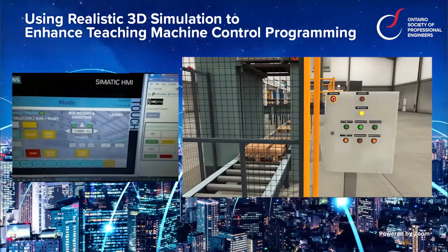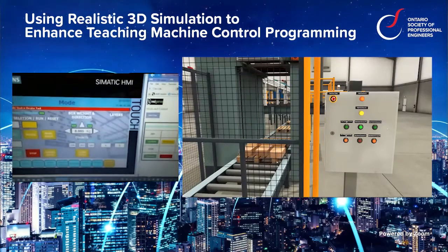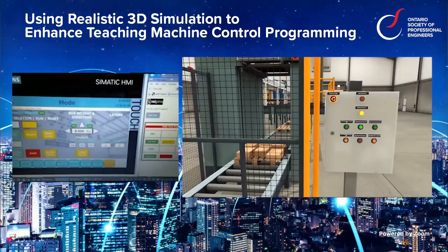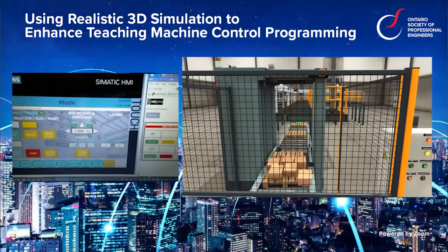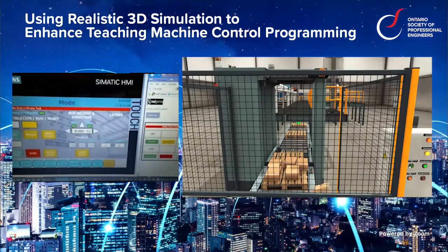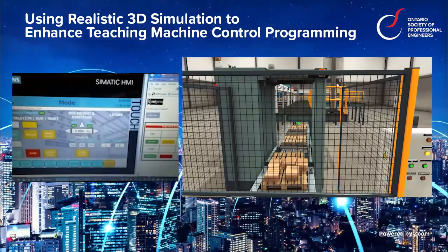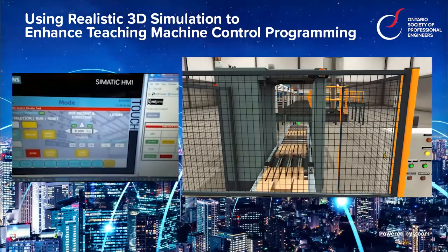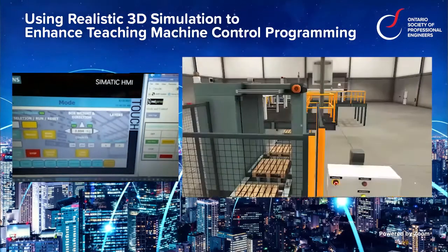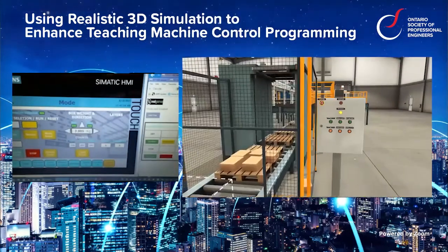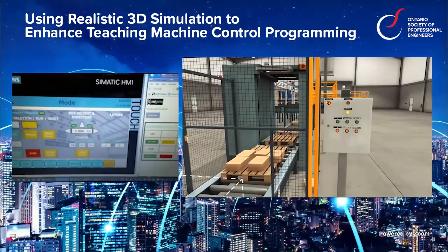And you see it's pushing, and because I've messed up on how I turned the motors on, the vibrations are pushing the boxes off the pallet. So again, they're reacting very much like you'd have in a real world, where you've got pallets running into each other. I've pressed the wrong buttons. I've done the wrong thing here in manual mode, and kind of demonstrate how important it is to create a system that an operator can't mess up. So I probably should have had some sort of sequence of operation on this panel, or some way to lead the operator along, pressing the correct buttons to make this work.